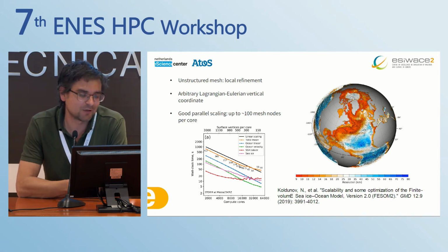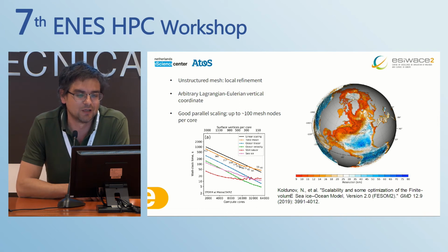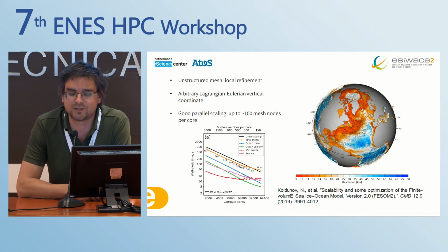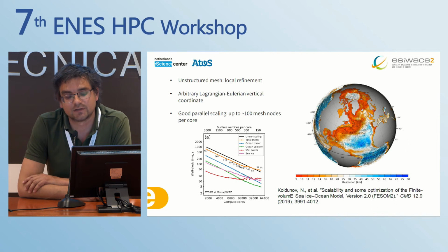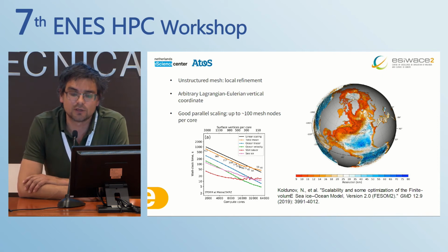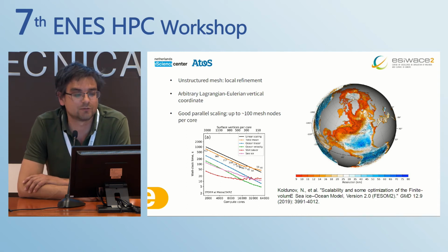What's special about FESOM is the unstructured mesh, I would say. The local mesh refinement is really the key strength of FESOM. You can refine the mesh along coastlines or through narrow straits. You can also look at sea level variability and have a local refinement to, for instance, resolve eddies. You see there a storm, or that's the XR grid, where you see a local refinement along the Gulf Stream and also in the Arctic to have a good ice influx resolution, I would say.